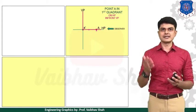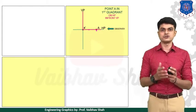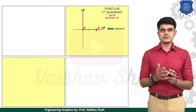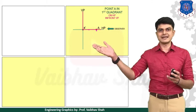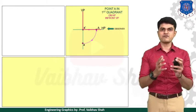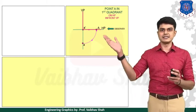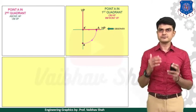Let us take the top view of this point. As your point is already on HP, you will have your top view lying on HP itself. Next step, we'll rotate this HP in the clockwise direction like this. So our final point would be point A on this vertical line. This is the final projection of a point whenever it is resting on HP but in front of VP.